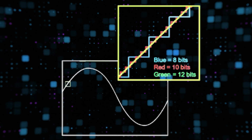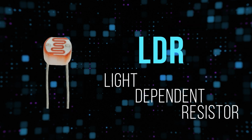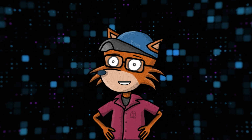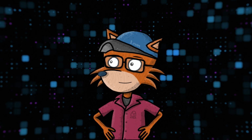A higher resolution means more accurate measurements, which is important when working with sensitive sensors like the LM35 temperature sensor, or an LDR, light-dependent resistor, where small changes in voltage need to be detected accurately.